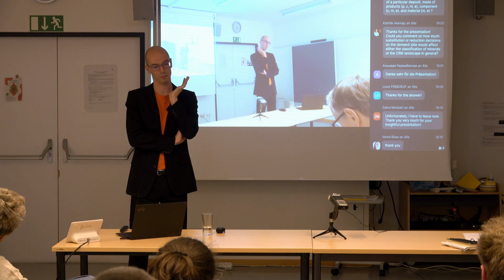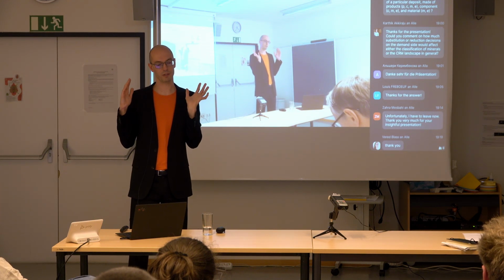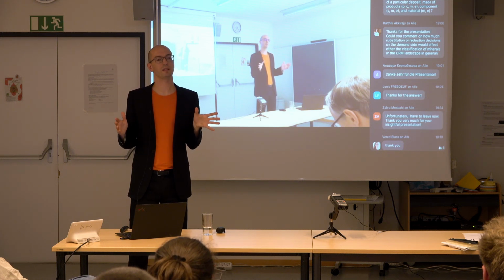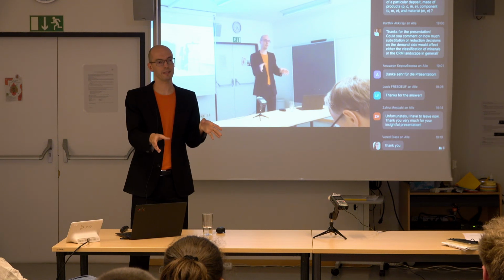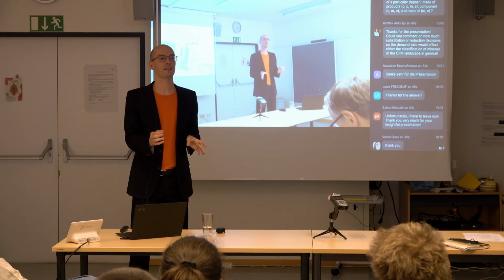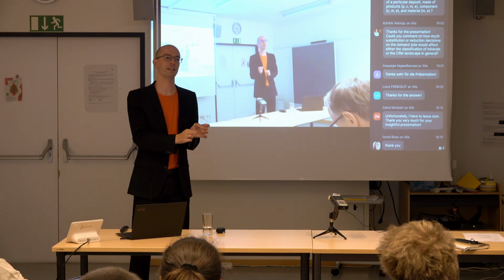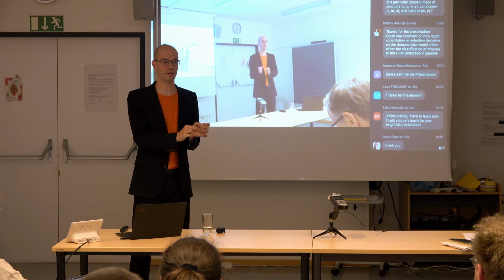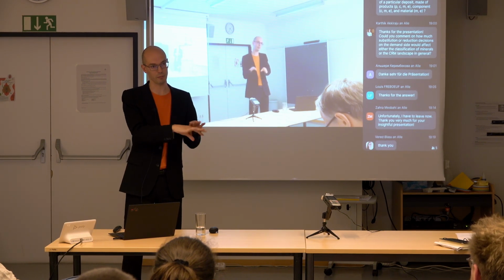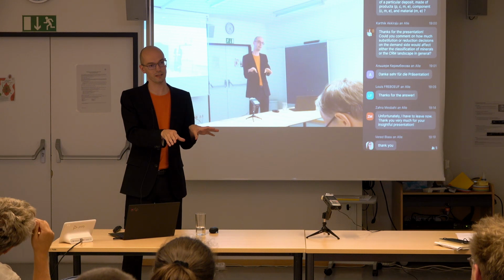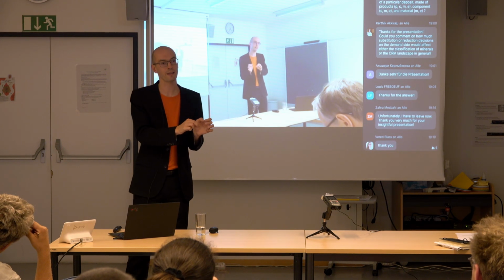One example: by now you can put aluminum scrap through a process. You put multiple cameras on it, multiple lasers. You smelt the surface very briefly and do an X-ray analysis of what this alloy is. You need to smelt the surface very briefly because aluminum has a lot of surface effects, so you don't want to actually measure the surface, you want to go a little bit below that.